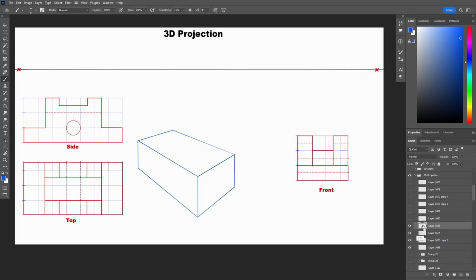A little more complicated shape than before. We have 3x7 units side projection, 3.5 by 7 units top projection, and 3.5 by 3 units front projection. The most visible projection that describes the shape is the side view. So let's start with that one. We need to divide the box from the side into 7 units and vertically into 3 units.